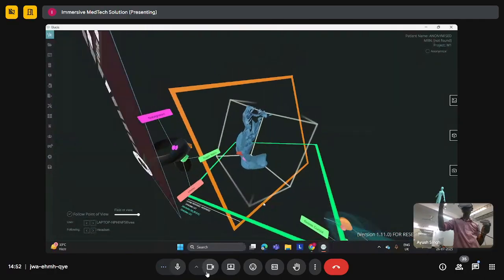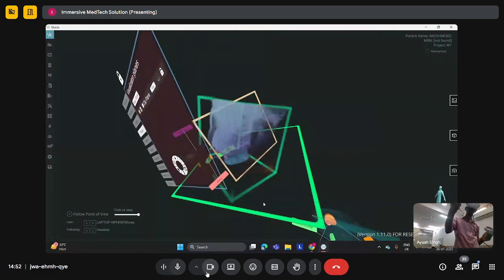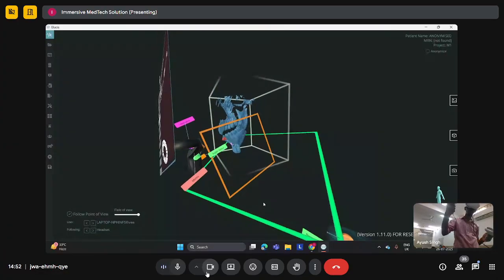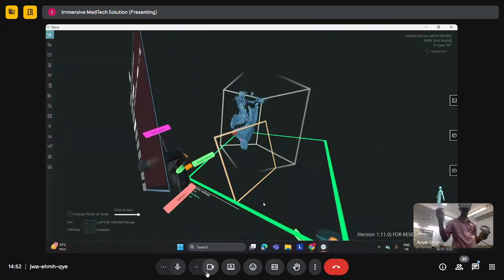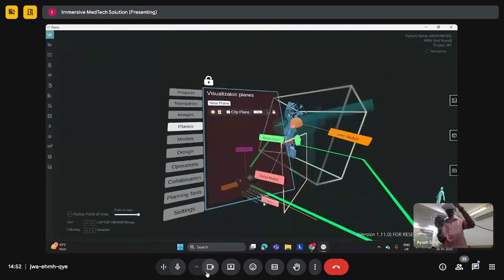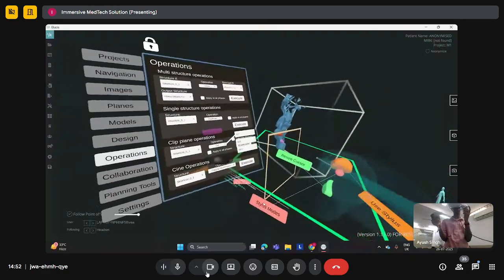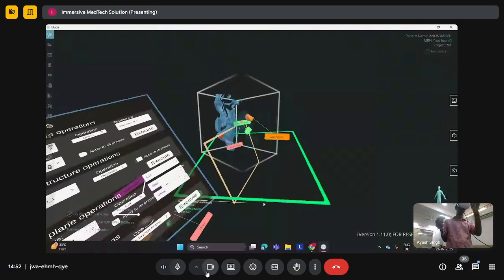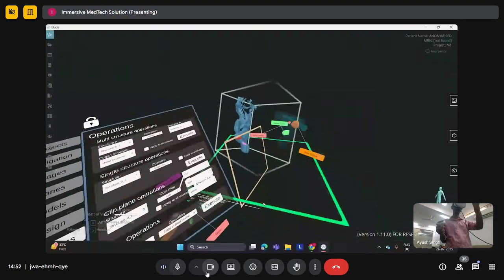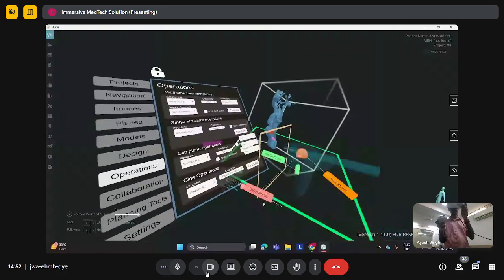So we can select out the asset points. We can also reduce from the size of the plane that we require. For example, if we need to focus on this particular part, you can directly select it over here. Once that is selected, going to operations, we have three modes of operations. Either I can cut this part, I can do the splitting into two different parts, or we can also mirror out the particular existing part over here. So there are multiple options that we can work.